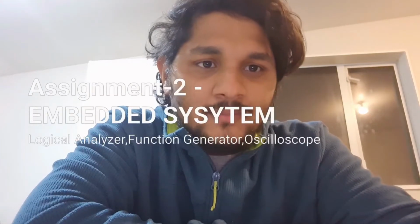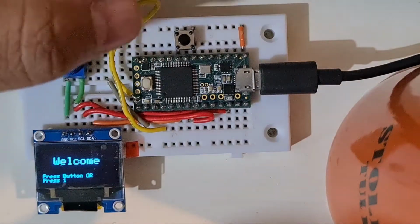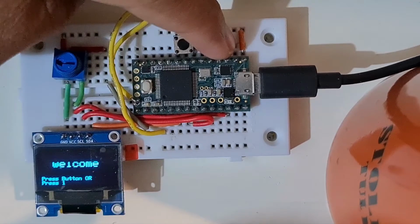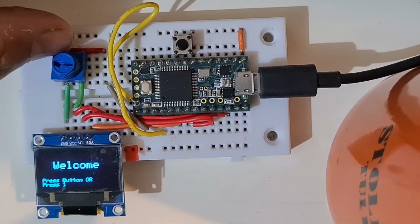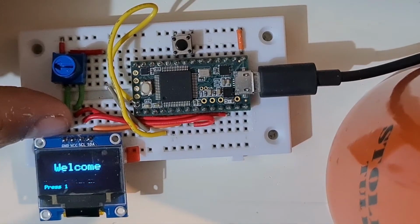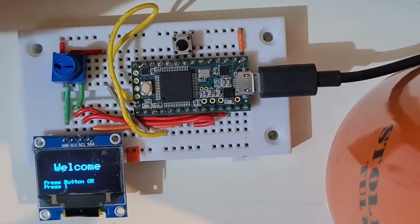Hi everyone, my name is Anandakrishnan and this is the second embedded system project. It is about a logic analyzer, oscilloscope and a function generator which can be made with a Teensy board and the help of an OLED. Here we can see the system: this is the Teensy 3.2, this is the push button, here we have the selector switch, which is a potentiometer, and this is the OLED, an SSD1306 display.